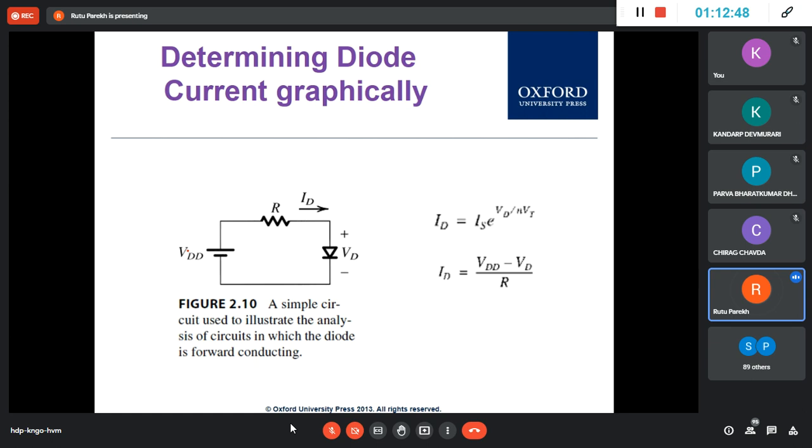That's the way we make the circuit. So here also, let's say any diode always has an R which protects the current through it, right? Otherwise it may get destroyed. So let's say this is a simple circuit where you have to determine ID, the diode current. Now you have a diode, R and VDD. And this is one loop only. So through a loop there is only one current, ID, everywhere. The same current is flowing through the same loop.